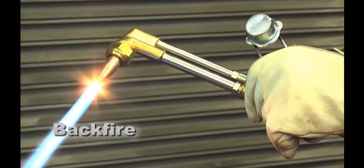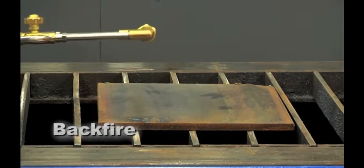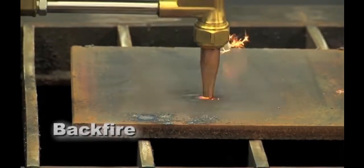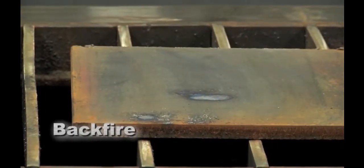Backfire is the return of a flame back into the torch, which produces a popping sound. The flame will either extinguish or reignite at the tip. This is normally the result of accidentally bumping the tip against the workpiece, operating the tip too close to the workpiece, or allowing the tip to become overheated.